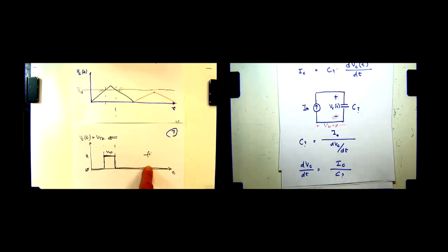So we somehow could hook this up, for example, to an LED, right? This output 0, 1, 0 volts and 5 volts, we could hook it up with an LED, don't forget the resistor. I think you built a circuit. Anyways, and then the LED would be lit whenever there is no finger, and the minute you put a finger there, the LED would turn off. Okay?